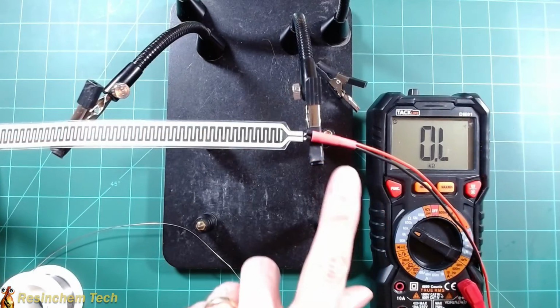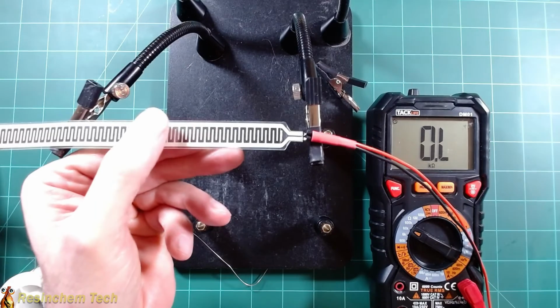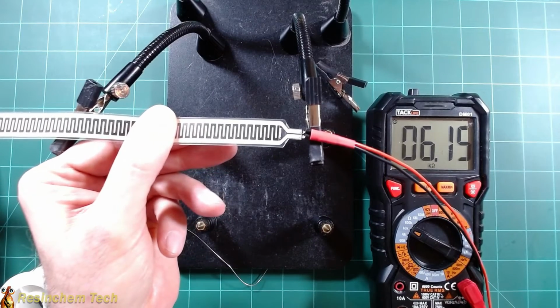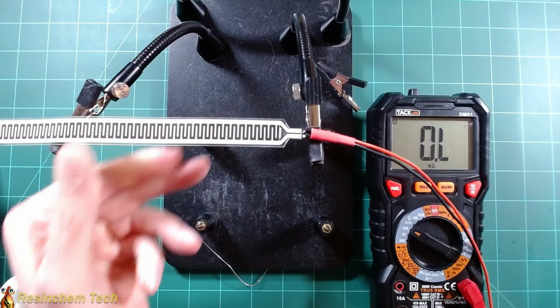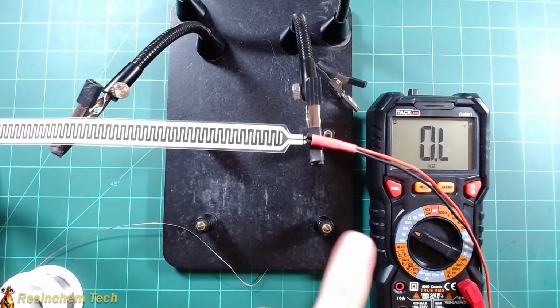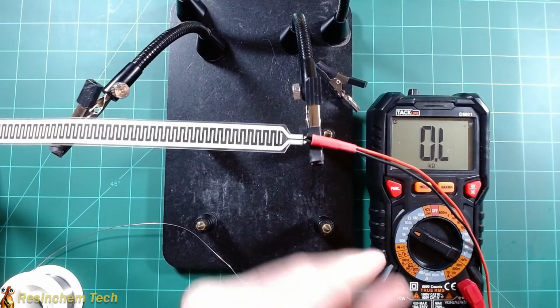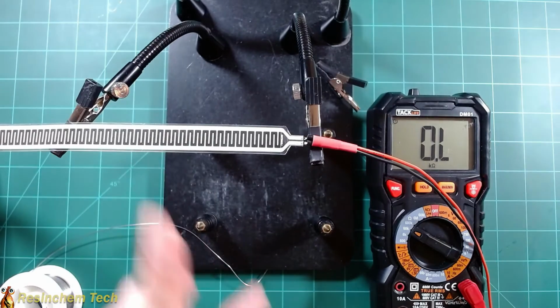All right, I put a little heat shrink on there, removed those from the clamps, hooked the other ends of our leads here back up to my multimeter, and hopefully we're going to see a different reading, and we do. The harder I press, the less resistance there is, so looks like at least we didn't damage anything with the heat. But now we're going to need to determine what resistor we need to add to this, to get the broadest and most stable range for our sensor.